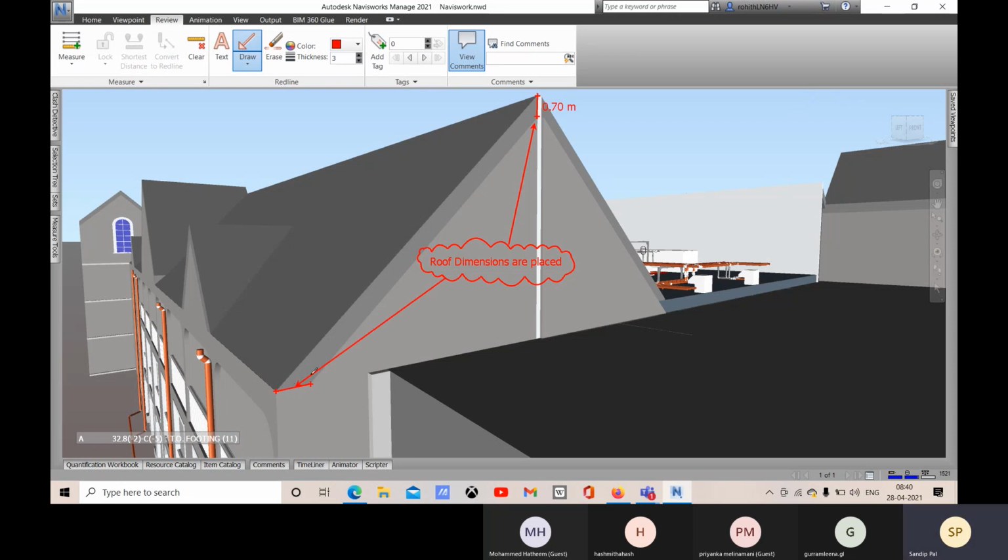Just to specify the two points. Okay, and as per this color you will have it. Let me show you again. Leg and then arrowhead. Okay, and you press enter, click on this select to escape. And if you want to erase anything, just click on this.